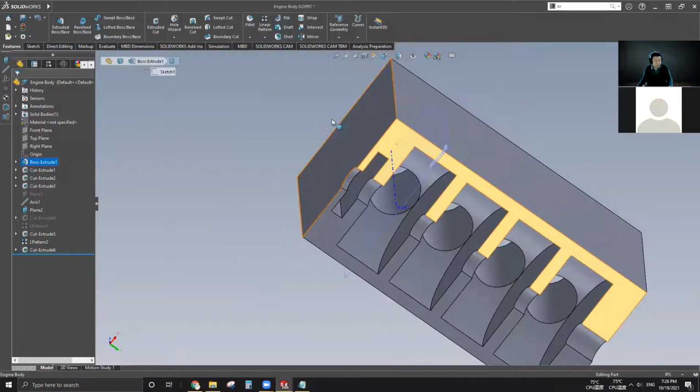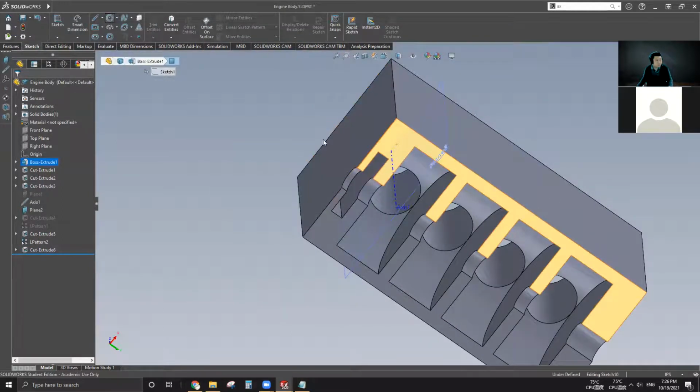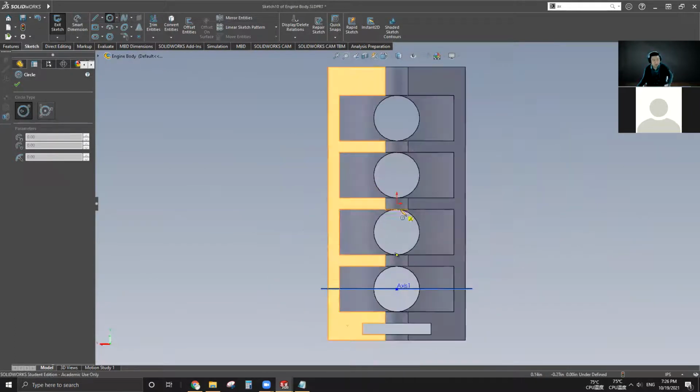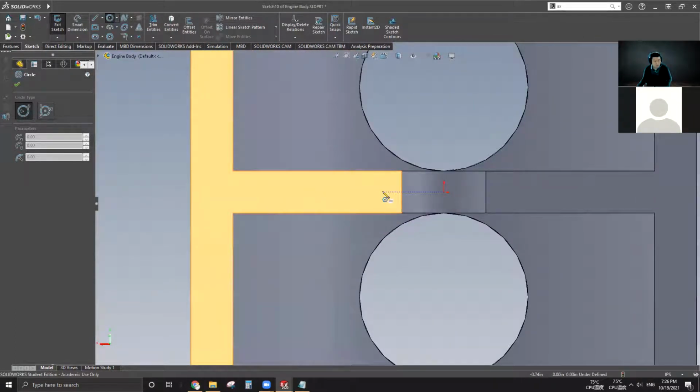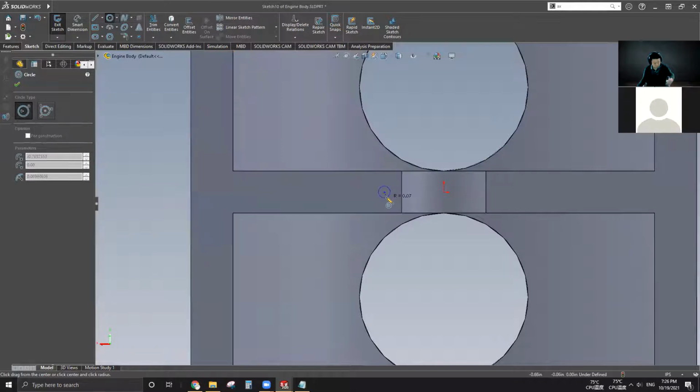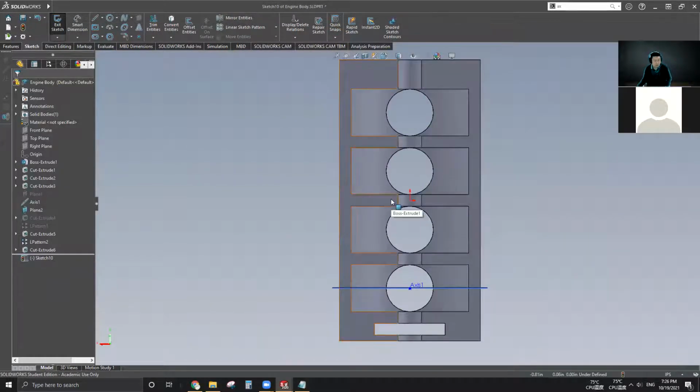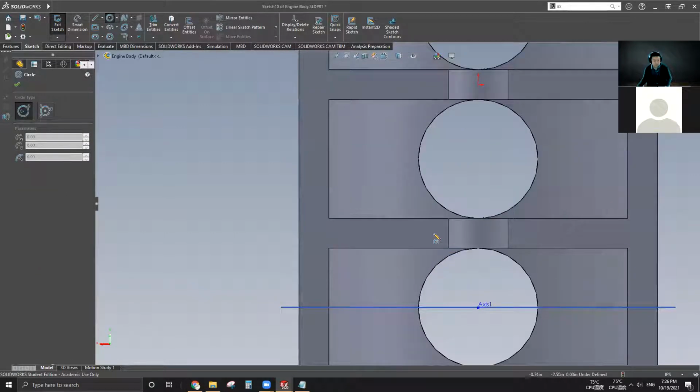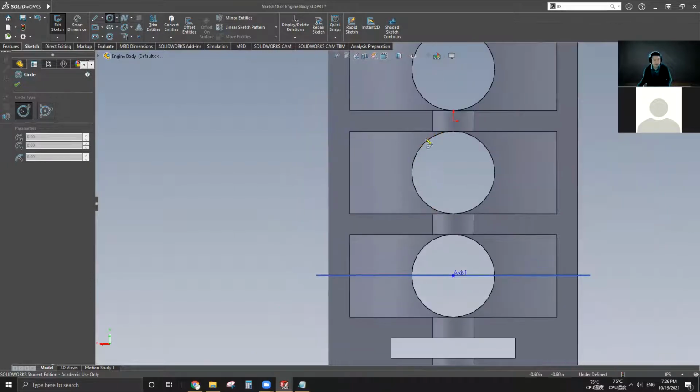All right, and we can start from this surface to make that little hole. Again, along the center line, but actually I don't want to start here. If I start here, I have to go both ways to make my pattern. So I'd rather start from the beginning or from the end, you know? But now I don't have any reference, because the center line only goes with the coordinates, right? If I go right here, I can have a center line. If I go right here, then I don't have a center line. So I need to make a center line.